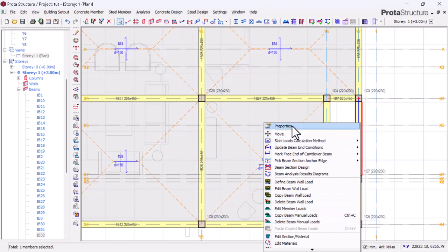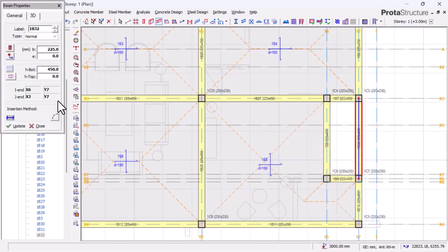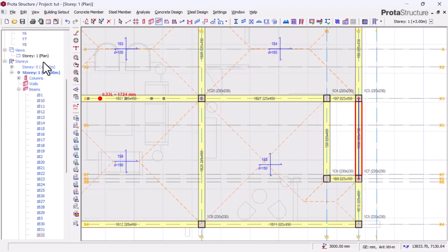So we go back to our plan and we take this off. Or what we do is we make it fit in, and we update. Checking this, we are reducing the depth of this beam. We're trying to reduce the depth of this beam such that it will flow with the slab we are going to insert. That is what I mean.